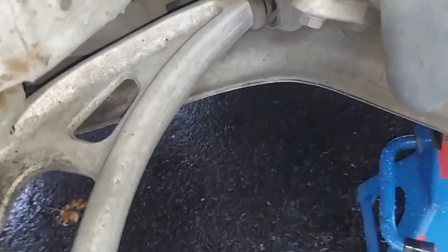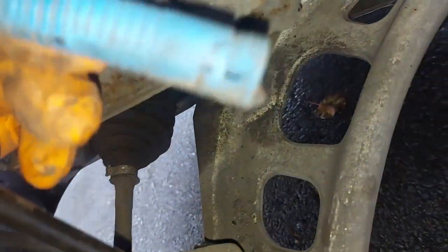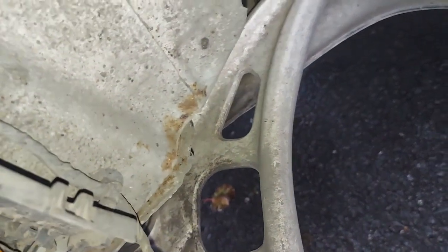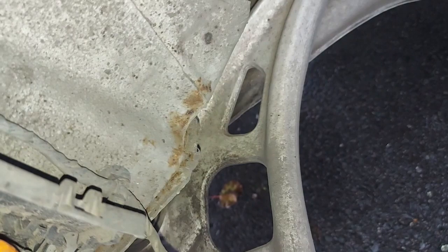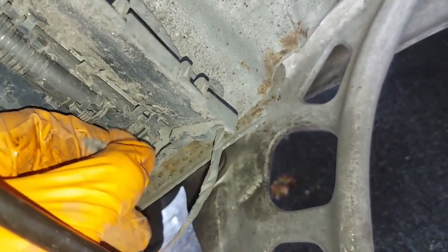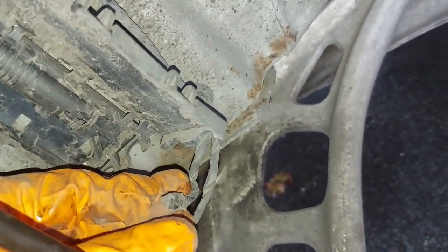You can see there are 2 wires going to it. I want to disconnect that and check for resistance first. If not, I'll put a scope on it. I'll check for voltage, but I'm not sure whether this one is the one that has voltage. Doesn't matter, even though it has 2 wires.